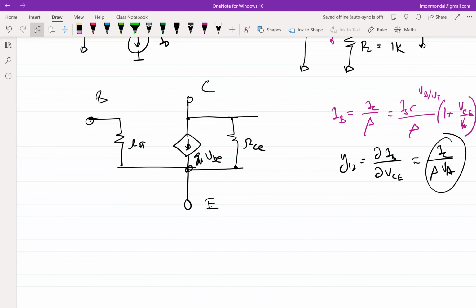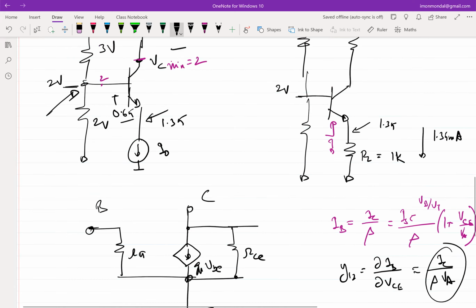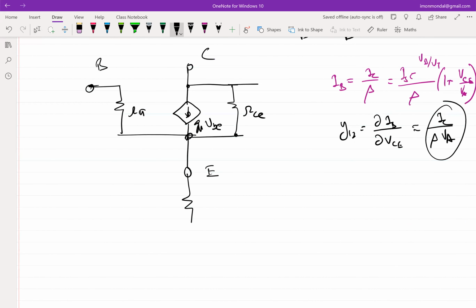Okay, fine. So now, in case of a MOSFET, if you had applied a test voltage, assume that this is biased in saturation and all. The equivalent of this circuit was you apply an RL here, and RL incrementally goes to ground. In case of a MOSFET, if I try to figure out the impedance looking in, this Rin was infinity because you are looking into the gate, correct? But in case of a BJT, it's not infinity because there is an r pi connected. So what is the effect of this?